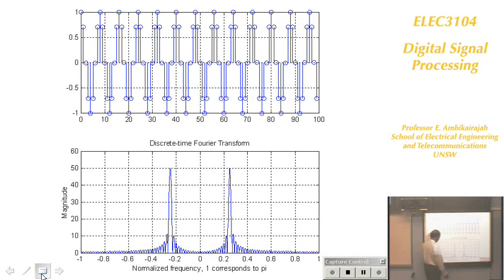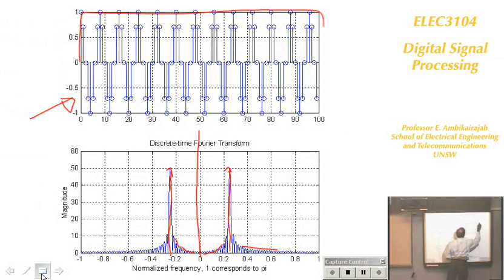This is another signal. This is a cosine waveform in MATLAB, and if you take the discrete time Fourier transform, whatever the frequency you work out, that's your center point. You get your signal there, at that frequency, and also symmetrically there as well. You will have all these ripples because you're taking a rectangular window, because you're grouping a signal from there to there.